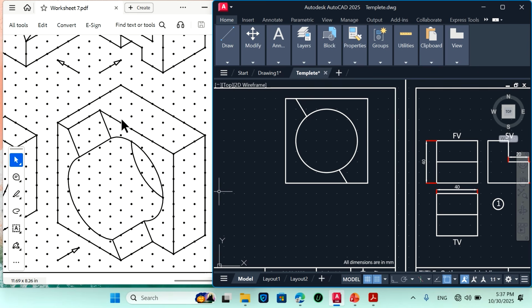So now I need to draw the top view of this shape. This is full width. Full width I already know, and the thickness is 1 2 3 4 5 6, 60 mm. So take a line command. With the full width I have drawn this, and with 60 mm, 1 2 3 4 5 6, and then 10 mm here and again 30 mm, 1 2 3, 30 mm, and I will be coming back here and complete this. So this is the principal surface which I can see in the top view. So these two are over.